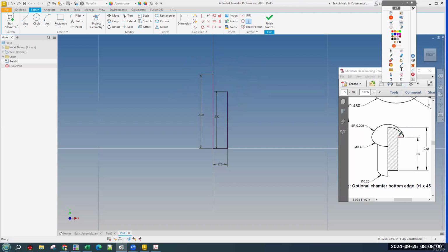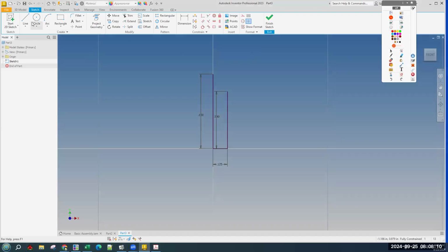We aren't dimensioning the length of this line to 0.2. We're dimensioning the distance from the end of it to the center axis. So it's going to be another 3-click situation. We need a line, snap to this end, and just make it horizontal and make it about the right size. Get the dimension tool, and we're dimensioning the end point of that line as the first click, and the center point as the center axis as the second click.